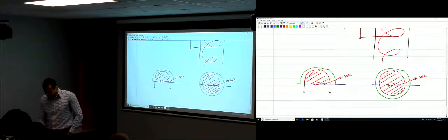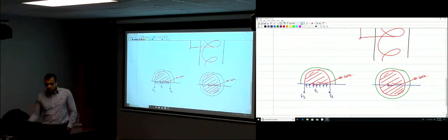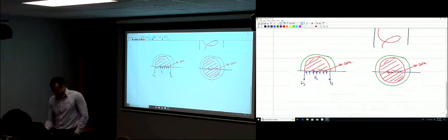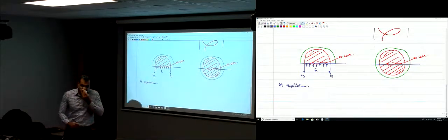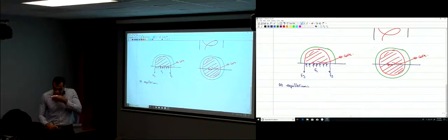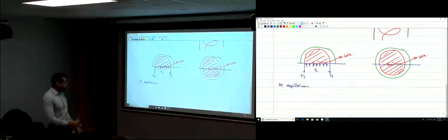So here the stress is F yield. This is the maximum stress that can be reached in those spirals. And this will put a confining stress on the core of the concrete. We're going to name this F2. That's the stress. So at equilibrium, we're always at equilibrium here, the tensile force in the spiral is equal to the force of confining on the core of the concrete.